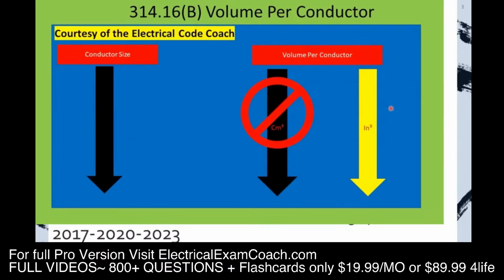Now let's look at the second table that we're going to be dealing with for box fill, and it's right below there. It's 314.16(B). And this one's very simple to understand. On the left-hand side is our conductor size, and on the far right-hand side is going to be our cubic inch volume. Every box can only handle so many wires and devices, and that's what we're going to learn in this lesson today.